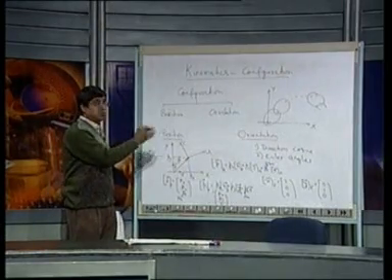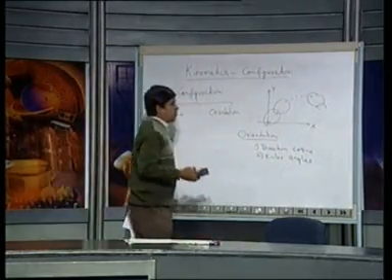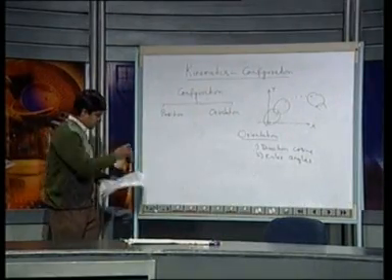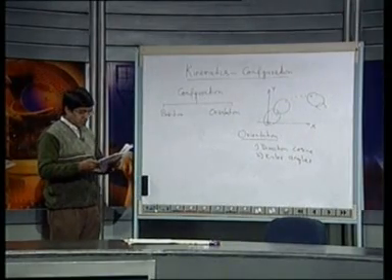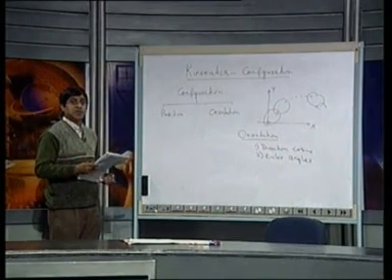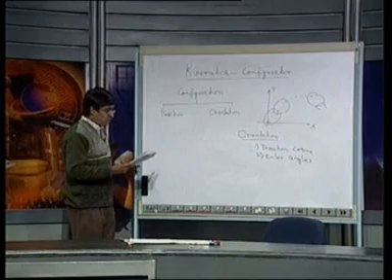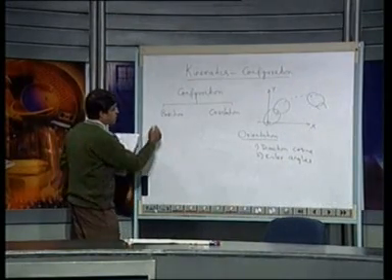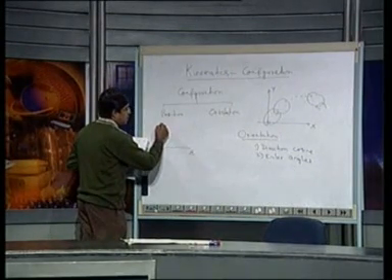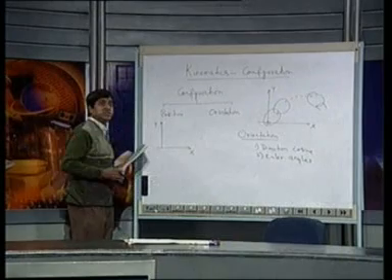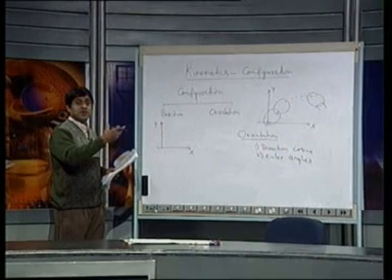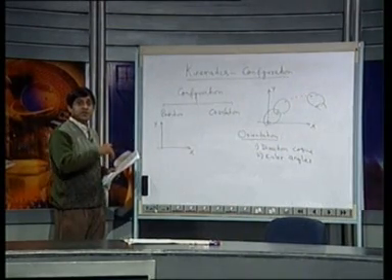Now, I will proceed to the orientation representation. For orientation representation, there are many ways. Here we will discuss two different ways of representing it. One is called the direction cosine representation and the other is the Euler angle representation. For the direction cosine representation, let me draw a fixed frame. I will show you with respect to the planar case only, and the development will be exactly similar for the spatial case, which is given in the unit.